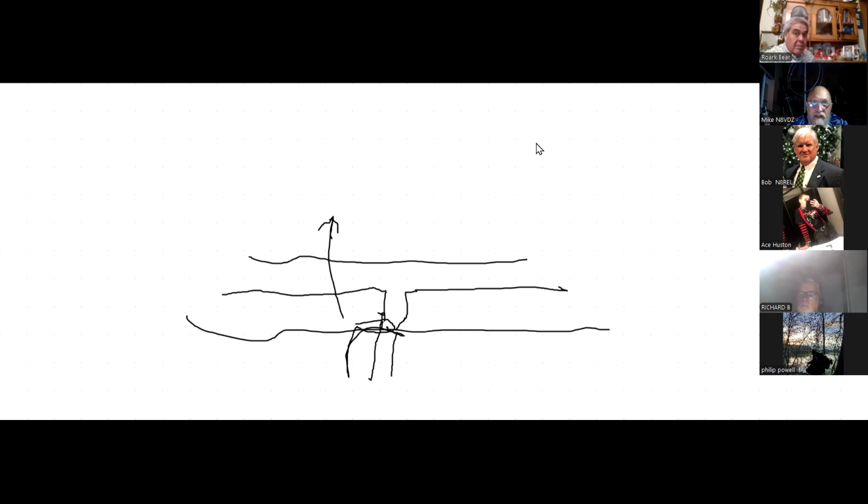While you're getting back out of this, Jerry, just one thing to add in with your question about why 50 ohms, Ace. All the radios that we use want 50 ohms. So that's why you want your line to your antenna and your antenna to be resonant with 50 ohms.